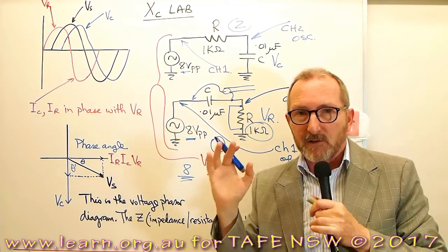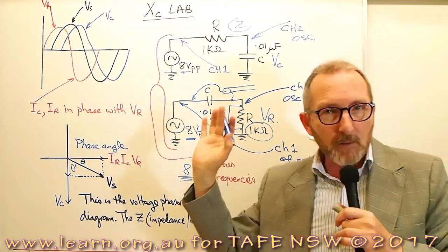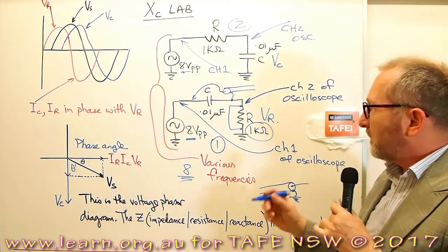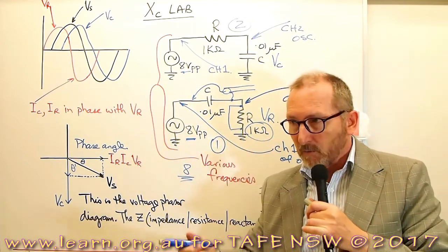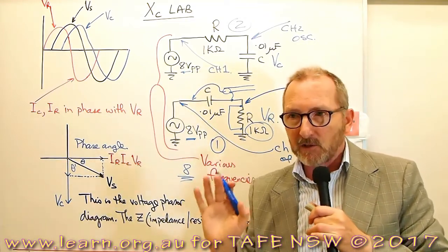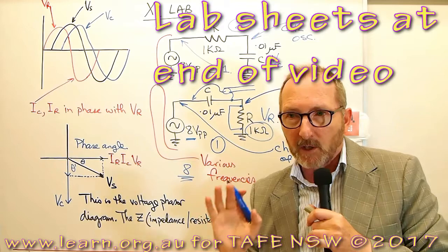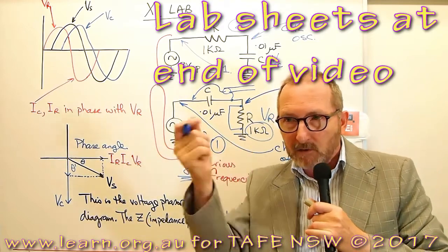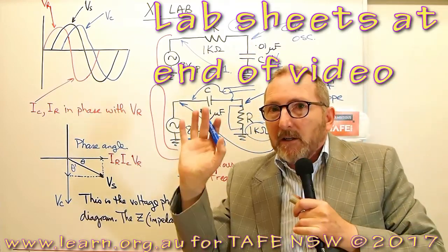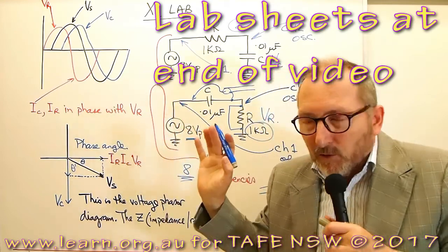If in fact we had an oscilloscope that was battery operated and therefore was not grounded, not a problem. We could simply put it across each component that we wanted to measure. But in this case, with an AC mains operated oscilloscope, which is grounded to all our other equipment, no, we cannot do that. And this hits us all the time in troubleshooting electronic circuits. We have to remember about the ground lead on the equipment and what we're measuring and where to put that ground lead. You never want to put it onto something that is actually a high voltage source, perhaps. You're going to end up in big strife, lots of sparks and lots of blowing fuses, and you're not going to feel real good about it.